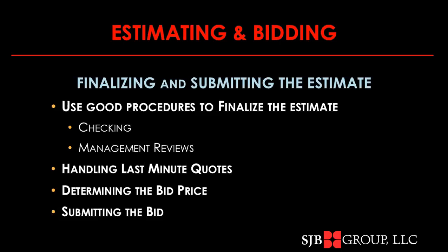In determining the bid price, we're going to do a final check of the recap. We're going to make sure we got all the adds and cut sheets accomplished. We're going to make a final assessment of risks. And then we're going to determine the markup. And usually that gets applied to the individual unit prices on the recap sheet.